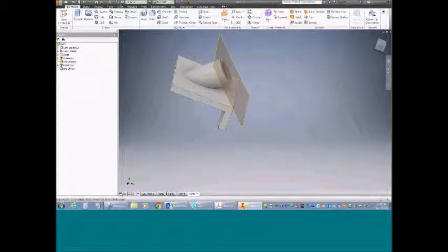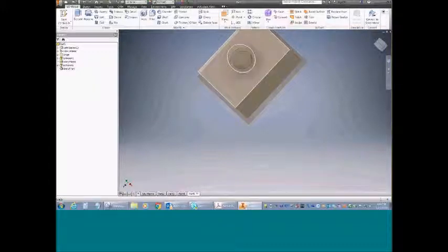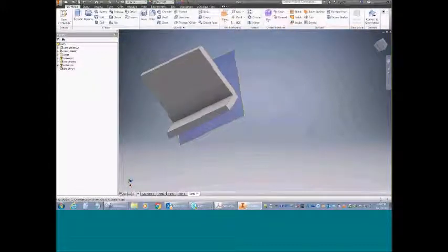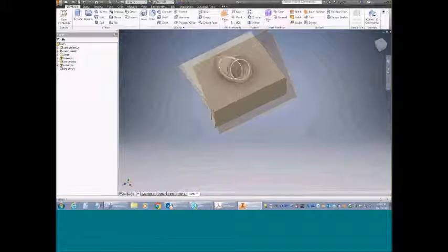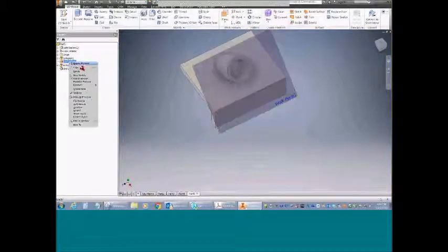But what they're perplexed about is that this circle did not go all the way through. It's still solid in the bottom because there was nothing there cutting. We were only joining at this point. So really, if you had some insight, the correct method would be to just put the outer circle up here, get a solid cylinder in, and then come in and do the smaller circle and have it extrude to cut all the way through this. So I'm not going to do that right now. I'm going to get rid of my work plane for just a minute here, turn its visibility off.